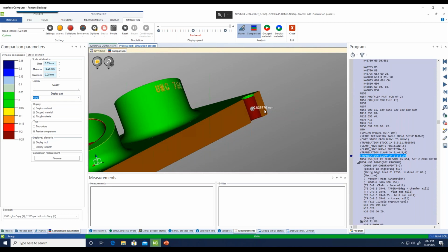So that's kind of your basic process that we do to get a job from the CAM system, import the ZOLLER tools, verify it for syntax, verify it for collisions, and then make sure that you're cutting a good piece. And then you can send this new edited file, because we changed that one value with the save program, directly to the shop floor and know that you could run that lights out first time.